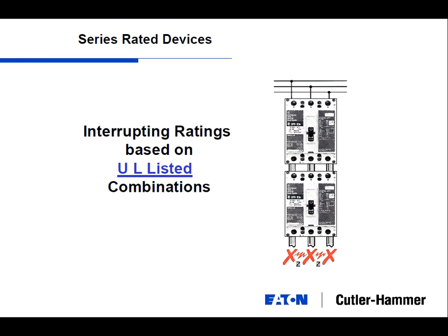Yep. Now, if you have a panel that feeds mostly motors, obviously, that's a good application where air handling units and chillers and all this stuff, where you have to almost have a fully rated system. But all your receptacle panels, correct me, Todd, if I'm wrong, all your lighting panels, almost always series rated, specified. That's a great application for series rated. Am I missing anything for lighting panel, receptacle panel, small appliances panel maybe?